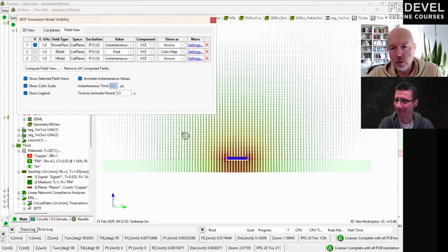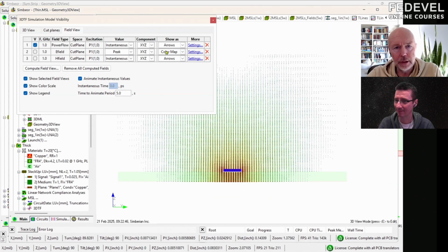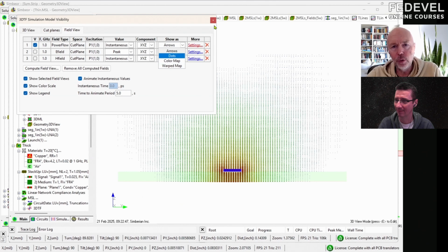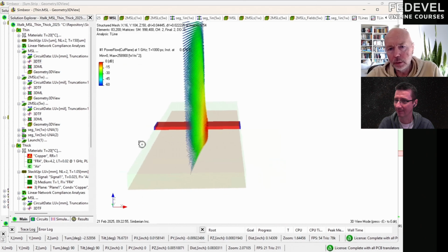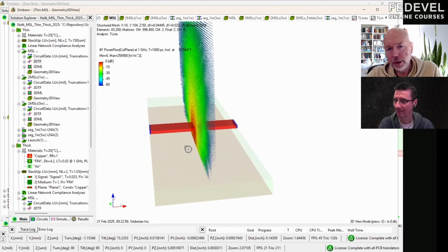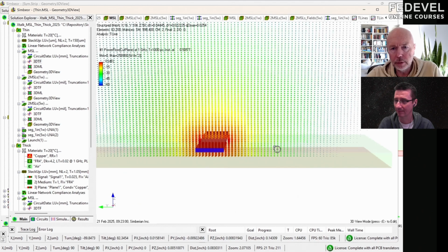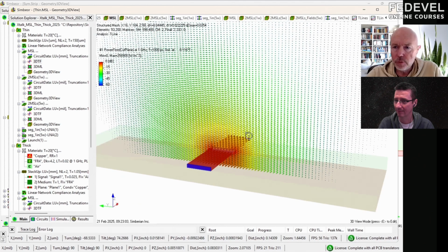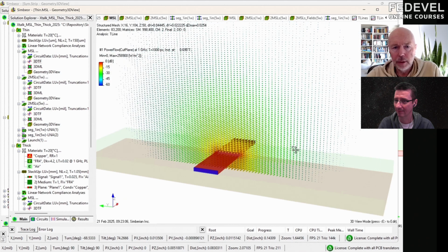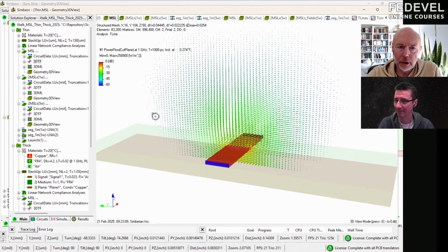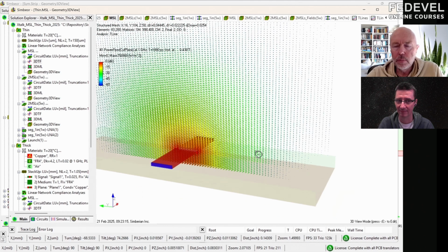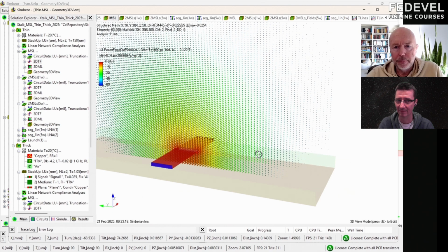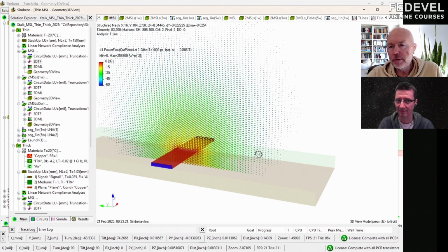So when we talk about crosstalk, you can see that in power flow, and the power flows along the structure. So now we look at the energy of the signal propagating along the track, mostly around here. And that's where the main energy of the signal is. But everything beyond this, all those green arrows and closer down to blue, this is the area where anything that gets into it is going to be coupled.